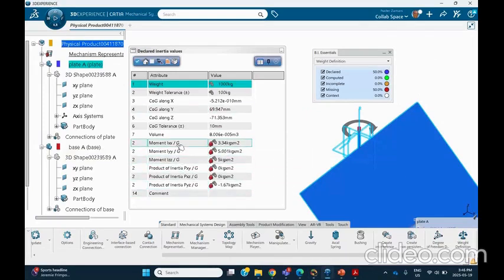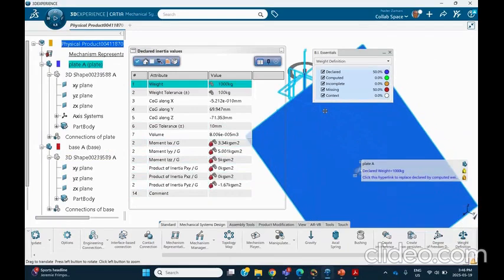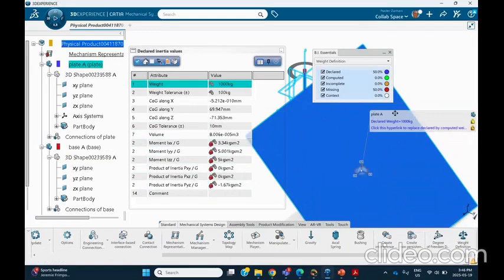Now, just be careful because these things are with respect to the coordinate system that passes through the centroid of that. It's with respect to these guys. Okay, just be careful. But anyway, so far theory agrees with our hand calculation, or with our 3D simulation. So far, these are okay.